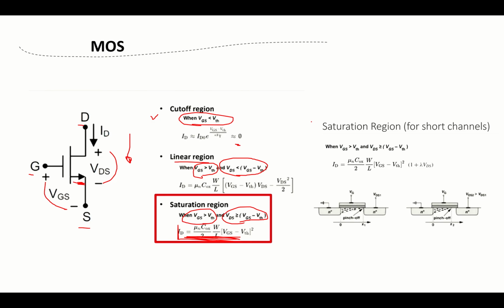Then there's another concept, the short channel effect. As we mentioned, if we keep reducing the length of the MOS, current will increase, but we have a leakage issue and worse power consumption for the current. But besides that, there are still other effects in the MOS, and there's a couple. This is only one of them, which is the short channel effect.